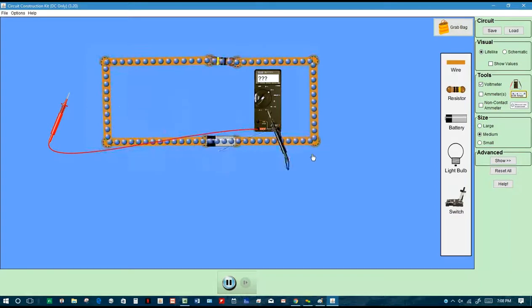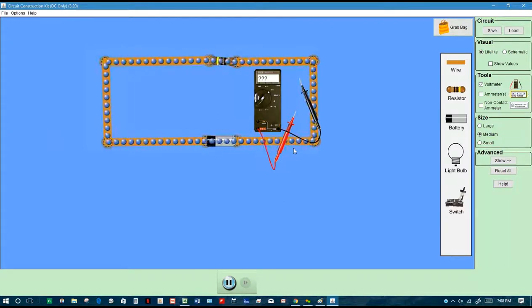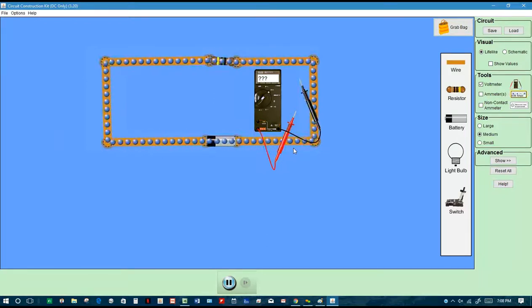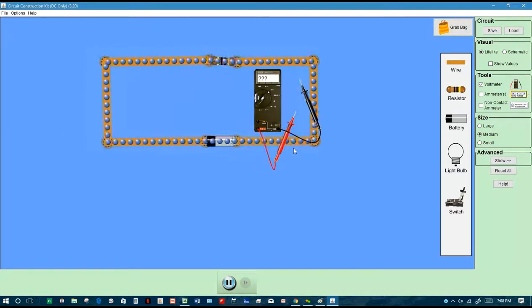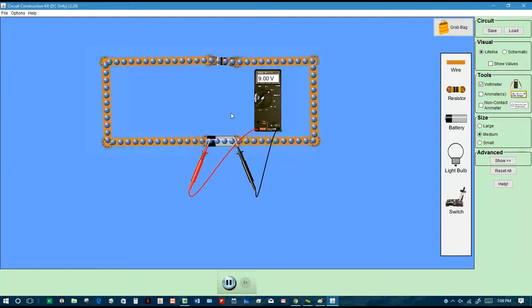Multimeter? Yep. So, if you went to Home Depot to buy it, they'll probably have it labeled as a multimeter because it can measure multiple things. It can measure voltage, resistance, and current, depending on which setting it's on. Some people also just refer to it as a voltmeter, but generally they're referred to as multimeters because they can do multiple things. So this voltmeter can be used to measure the voltage of the battery, and you would take these, they're called leads, and you would touch one to each end, and it would tell you what the voltage of the battery is, so you can see it saying 9 volts, right?